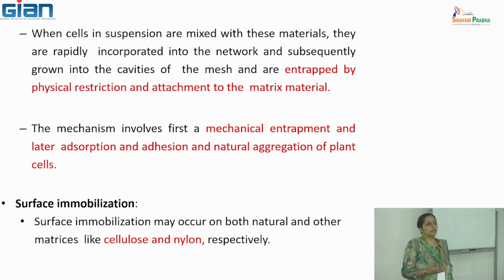Now, fluidized bed columns are again a technique common to both immobilized microbial systems and plant cell systems. The basic difference is that in fluidized bed systems, you make use of either counter current or same direction currents. You use gases to mix with the liquid substrate stream, such that there can be recirculation happening, which can cause better mixing.